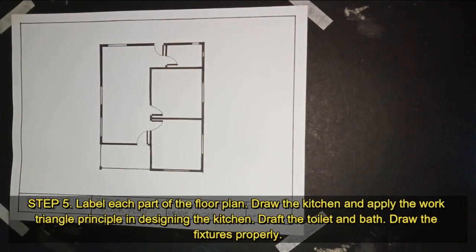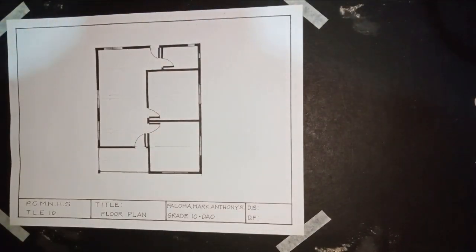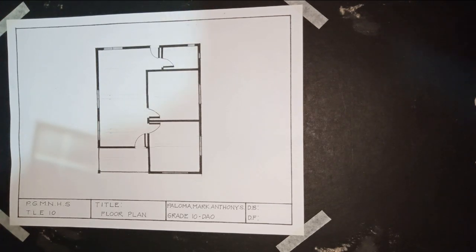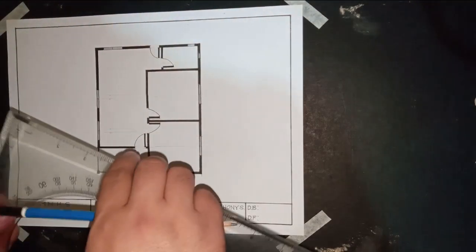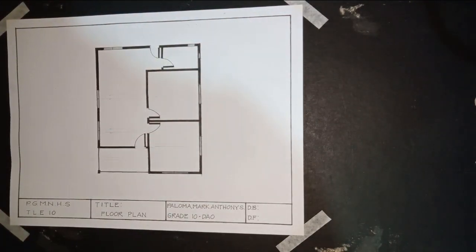Step number 5. Label each part of the floor plan. Draw the kitchen and apply the work triangle principle in designing the kitchen. Draft the toilet and bath. Draw the fixtures properly. Make sure that you draw a guideline first, before you label the drawing.